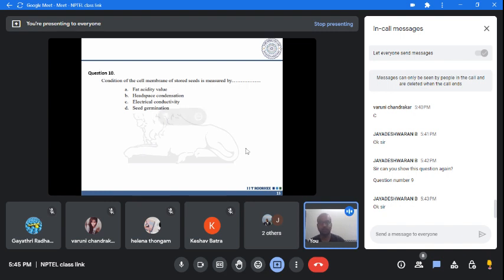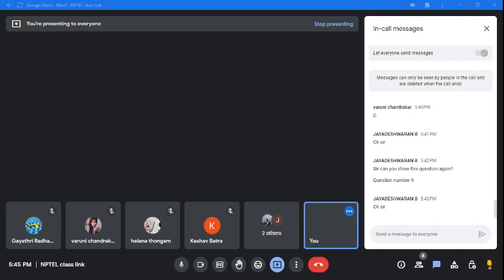Okay, you're asking to show the question 9 again. Okay, so 2 ton of grain stored in a bin is cooled by aeration with ambient air at 30 degrees centigrade at a volumetric flow rate of 0.22 meter cube per minute per ton. The specific volume of air at 30 degrees centigrade is 0.91 meter cube per kg.